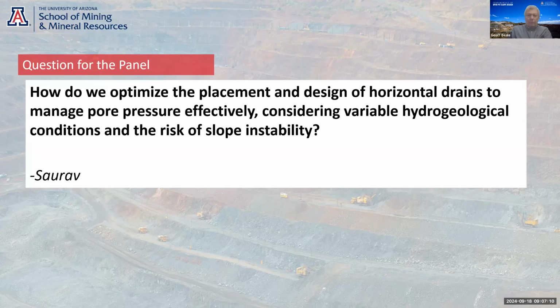And I was just saying to them, we're at the Morenci mine in Arizona at the moment, and we were just saying to the guys yesterday to start thinking about putting in some more horizontal piezometers as part of the drain drilling program. I think more and more sites now are putting in multi-level piezometers in horizontal holes. Particularly where you have slope parallel structure, you can put the piezometers in conjunction with a TDR cable that measures the downhole shear. And if you put those in horizontal holes, that gives you great information, not only on the pore pressure, but on any potential deformation behind the slope.